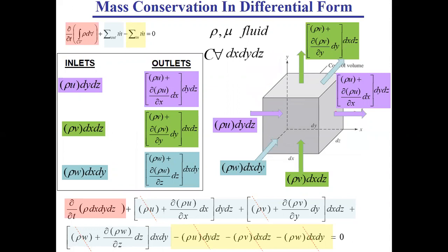We'll go into more detail when we review the conservation equations, but just to summarize the procedure: when I want to get the momentum equation, I base myself on Newton's law. So I write sum of forces equals ma on this element. And when I do this, I should consider all external forces acting on my element, and to have a general case, I should consider all possible types of forces.